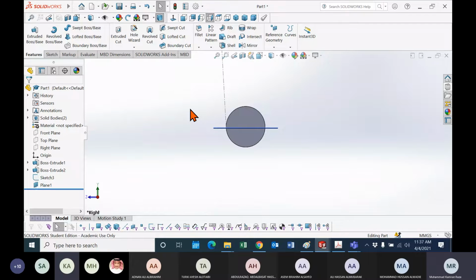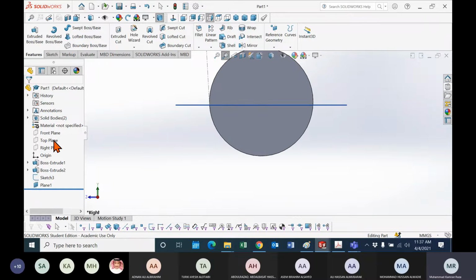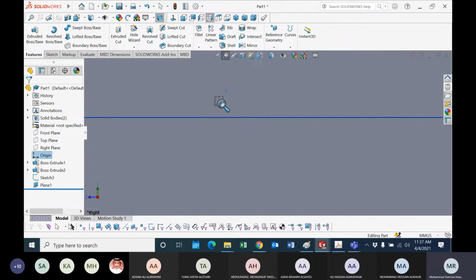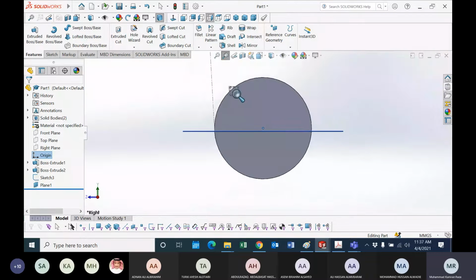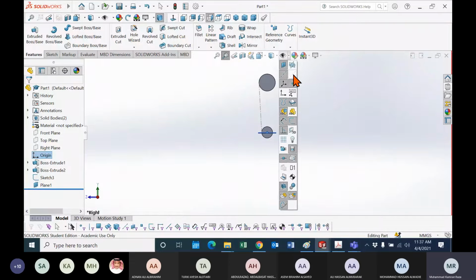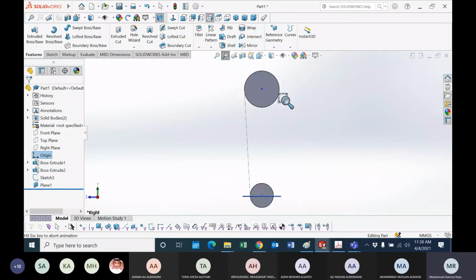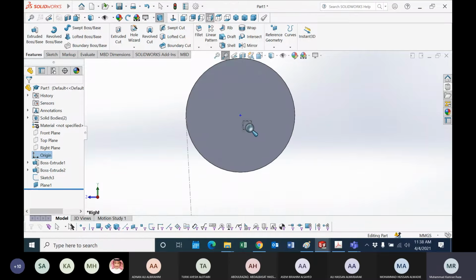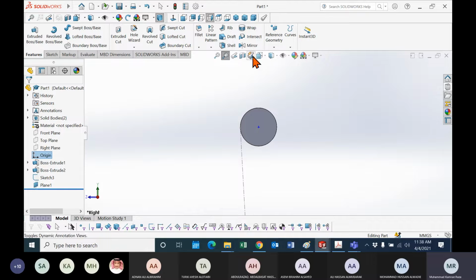Not in the center, doctor? Not in the center. That was the reason why we drew this line. You can see it's slightly less than the center. The origin is at the center. See, maybe a small 2 millimeter distance, but it's slightly different. Similarly, the upper one is also different. If you see the center of the origin, this is the center. Again, slightly less than the center. So now we are inserting the plane exactly on this point, where this line is tangent to this one.